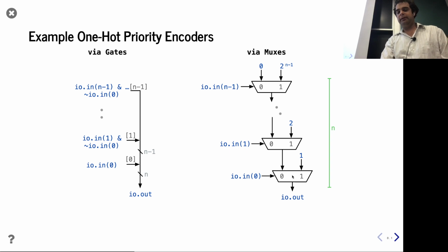So with the muxes, let's say, for example, we say that the lower the index is, the higher the priority it is, right? So index 0 has the highest priority, right? If that's the case, you can see that no matter what's coming in on this input, if this input is 1, this one's going to win out. It's going to say, hey, that bit's the one that matters. And it's because it's later in the chain, right? So we can override other ones, right? In this one, we're saying n minus one is the lowest priority, so that way, it can get overruled, so to speak.